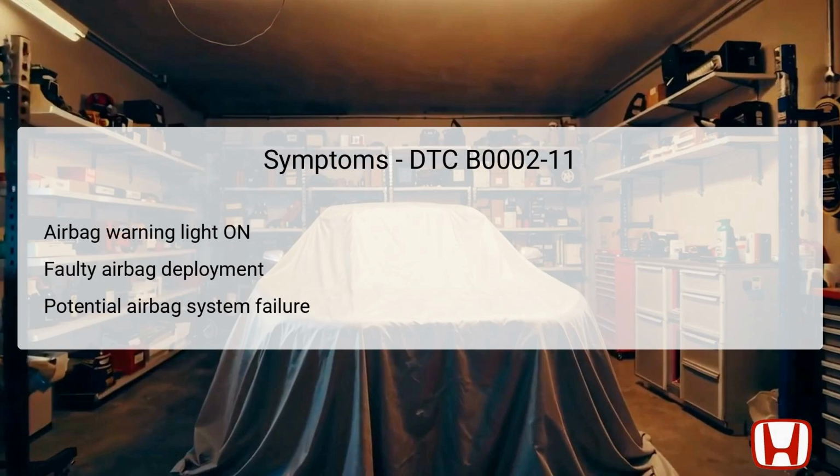The symptoms associated with DTC B0002-11 can manifest in several ways. One of the most immediate indicators is the illumination of the airbag warning light on the dashboard, signaling a problem with the SRS. This warning light serves as an alert to the driver that there's an issue needing immediate attention, as it directly relates to vehicle safety.